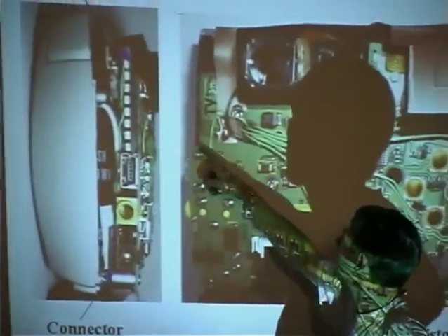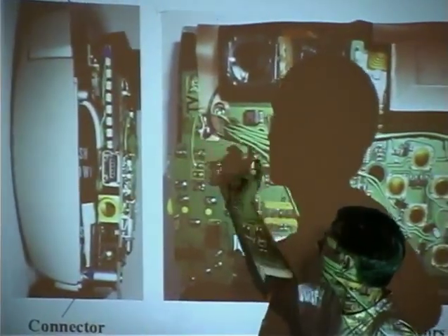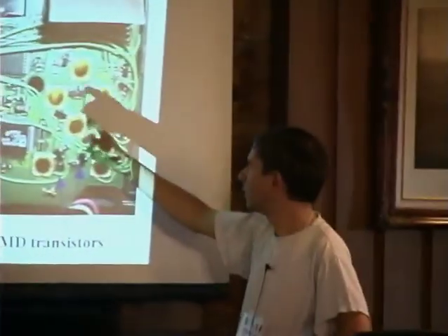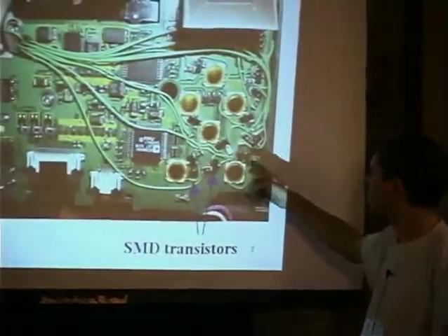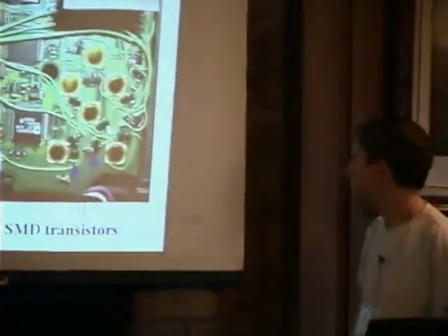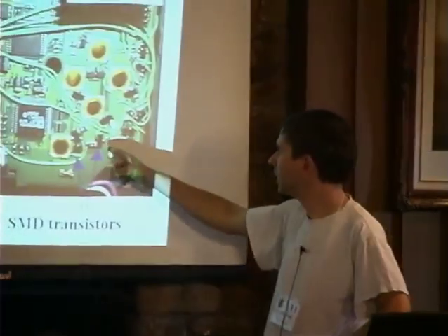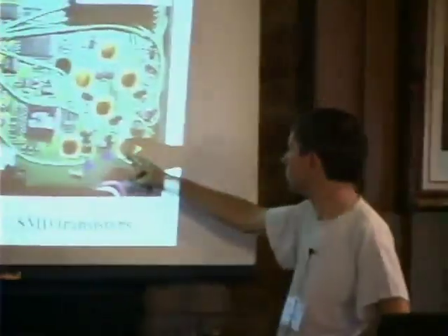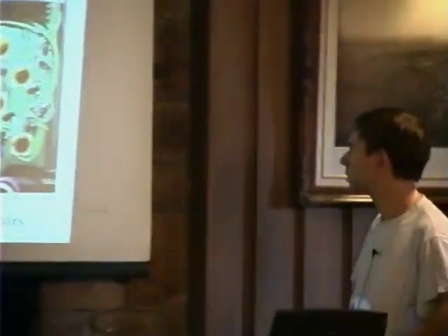Between the microcontroller that you can see here beside the PCB, there are 10 wires for the 10 switches, and for each switch there is a surface mounted transistor and a small resistor, to command the switch.